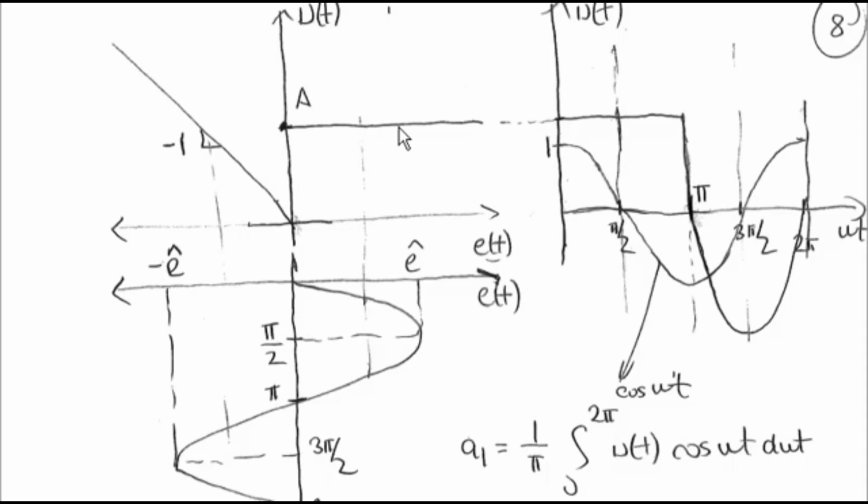With hysteresis type of nonlinearities, for a single e value, I can have multiple u values depending on the derivative of the input. This dependence on the derivative is some form of memory. So for those type of multiple valued nonlinearities, for nonlinearities with memory, we will have complex describing functions. But you see that for this nonlinearity, for each e value, I have a single u value on both sides. So this is a static nonlinearity.